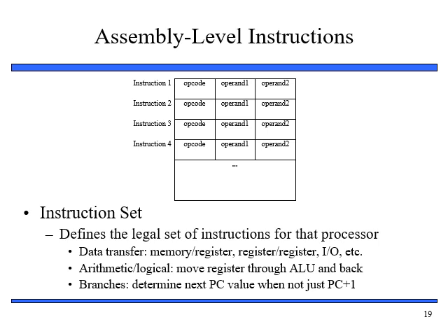Now an operand field specifies the location of the actual data that takes part in the operation. The source operand serves as input to the operation, while the destination operand stores the output. The number of operands per instruction varies among processors. As we can see in this slide, we have two operands, but it is not necessary to have two operands. We can have a different number of operands, depending upon the processor. Even for a given processor, the number of operands per instruction may vary depending upon the instruction type. So that was about the instruction set.